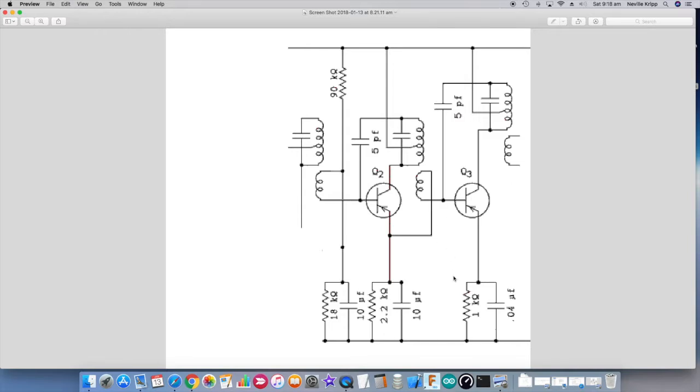And again, the rest of the circuitry that we have here is basically just biasing the transistors into the linear operating zone. So some emitter resistor and decoupling in both transistor emitters, and then we've got some resistors here in the base circuit just to set the device in that linear operating zone. So that's two examples of the IF stage, in a valve or tube situation and in a transistor stage.